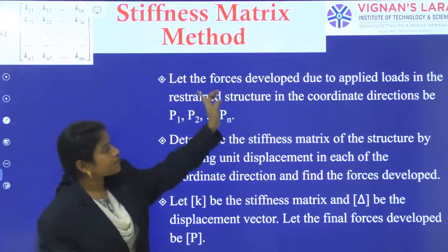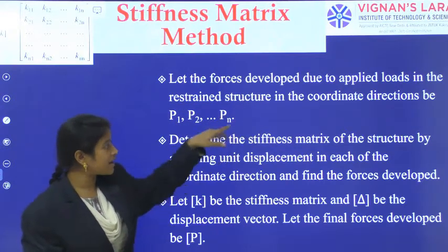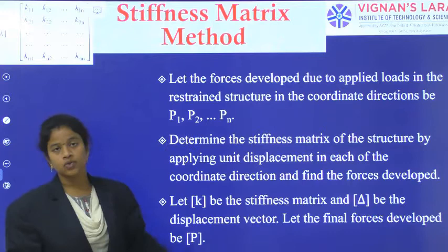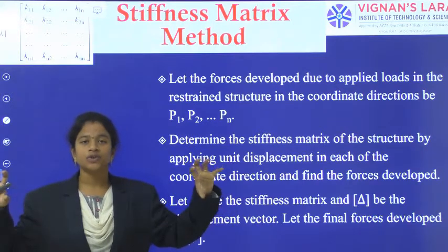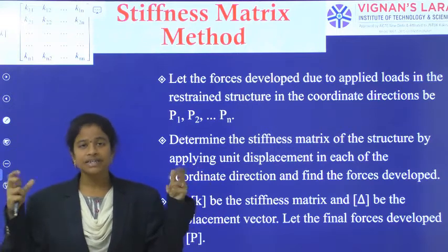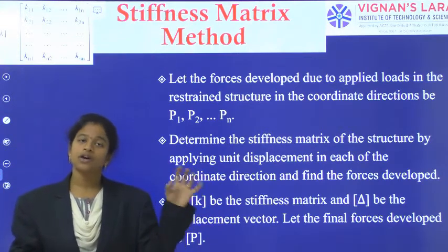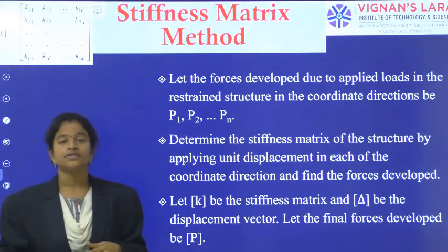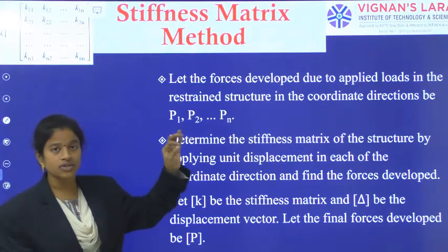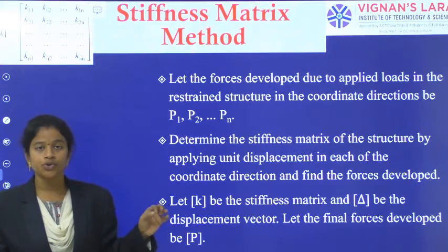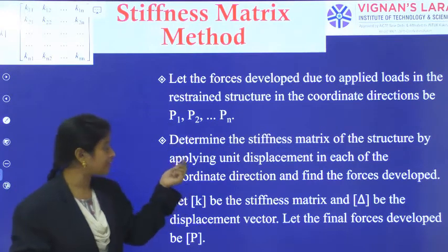Now, let the forces developed due to the applied loads in the restrained structure, in the coordinate directions, be P1, P2, P3 and so on up to Pn. As I am restraining all the supports, due to that restraint some forces, resisting moments or reactions at the supports will be generated. The forces generated due to the restrained condition are P1, P2, P3 and so on, Pn.